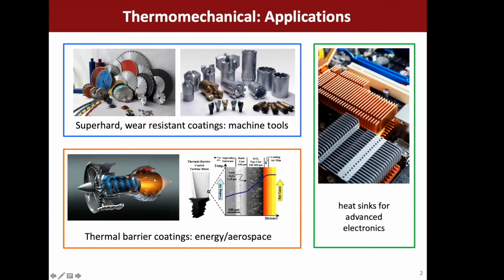So these can corrode these turbine blades. Also, the higher the temperature you have, the more efficient your engine is going to be. So you want to try and increase the temperature that your engine operates at. In order to do that, to protect the turbine blades, to stop them from melting or deforming or corroding, you want to use these thermal and environmental barrier coatings.